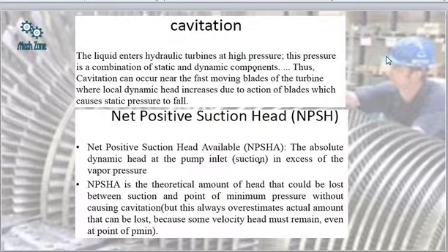As a result of cavitation, the bubbles which are formed collide against themselves and burst. When these bubbles burst, they produce very high energy pressure waves, which mainly cause the pitting action.